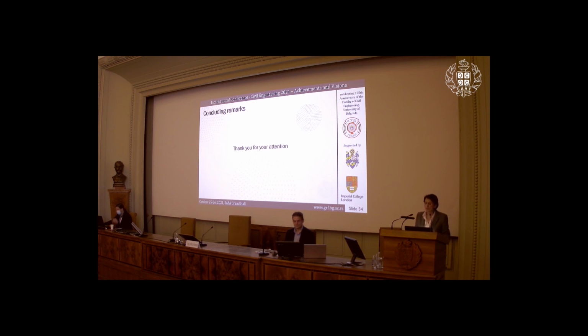For example, the Crossrail tunneling that was recently going on in London was very much monitored. The whole of the London Basin was followed by InSAR technology, and it was able to show the red patterns where settlements of the ground surface were noted during the construction.